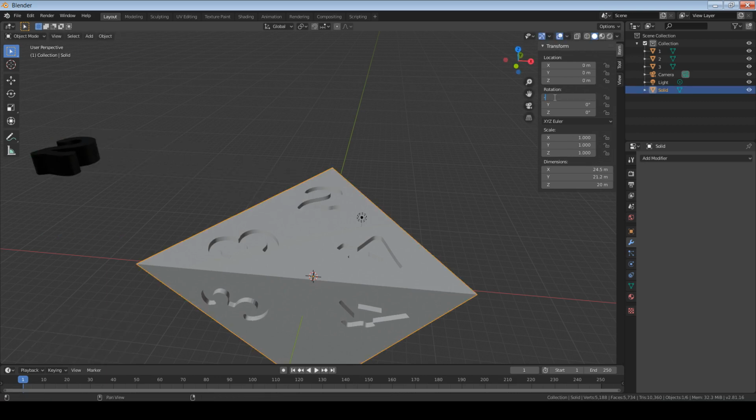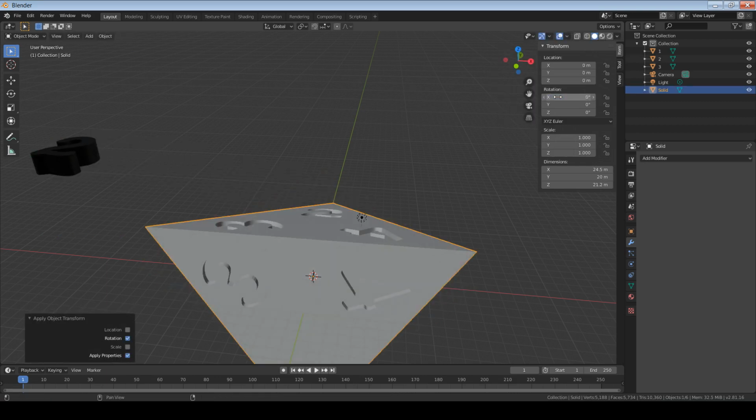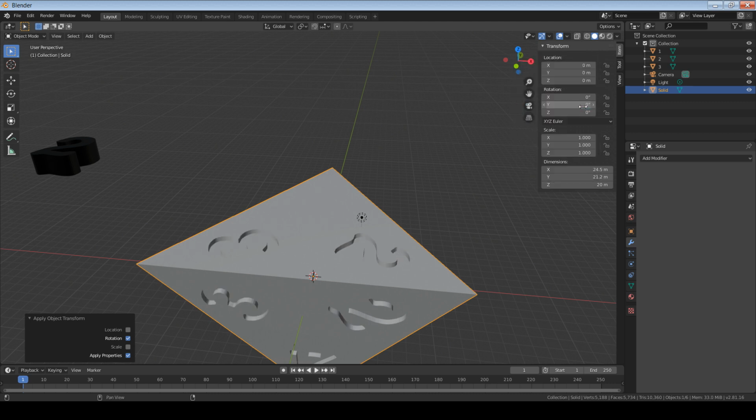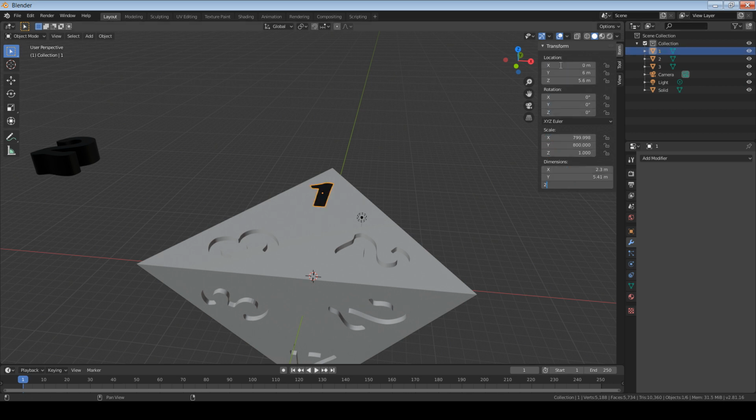To bring up the blank corner where you're going to be putting the number 1, first rotate the D4 by negative 19.47 degrees on X, 120 degrees on Y, 19.47 degrees on X, and then negative 120 degrees on Z, making sure to apply after each rotation. Now repeat the steps with the number 1 that you did with numbers 2 and 3.